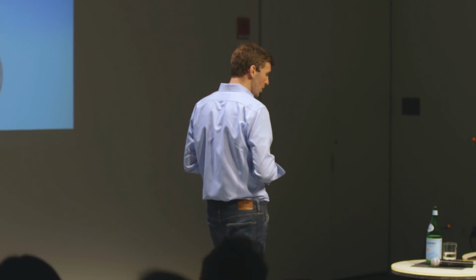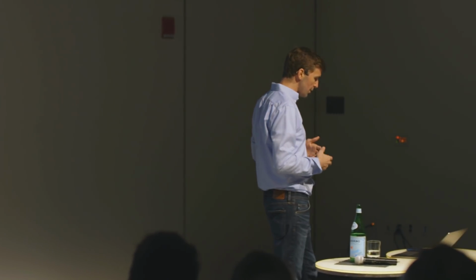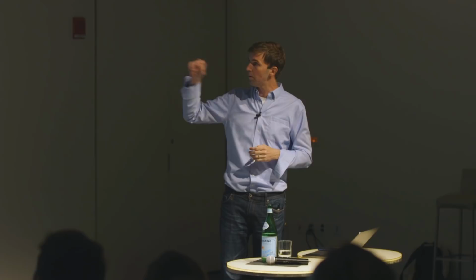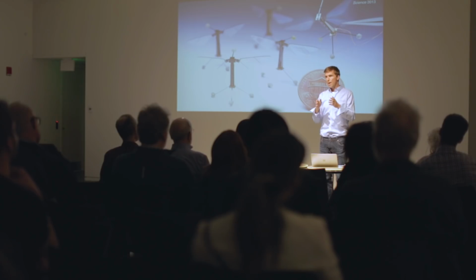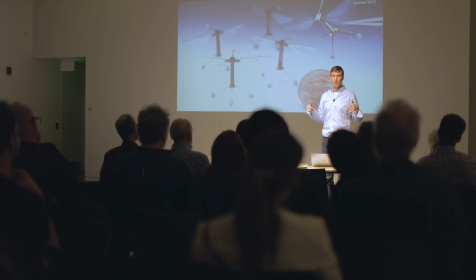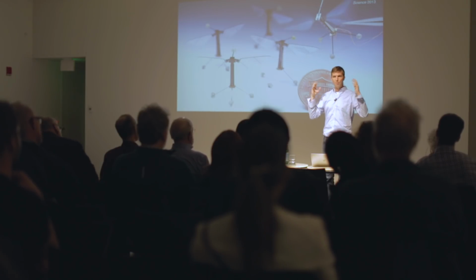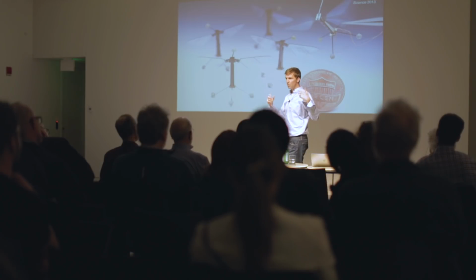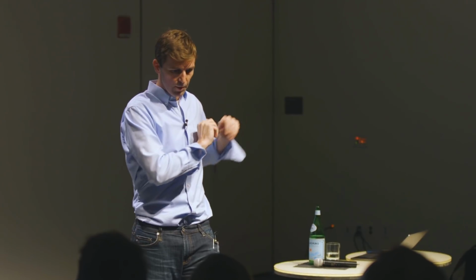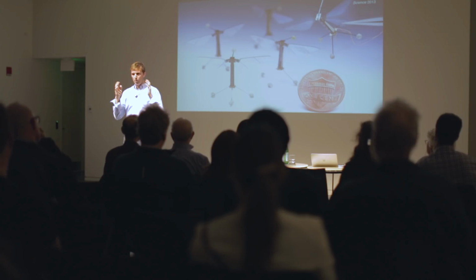So then the question of design. How do we actually think about designing these systems? This is a very simple device. The way that it works is I cut the robot down the middle, and I have an actuator on either side, and that actuator is basically just a little artificial muscle that's doing this. That very small motion is then mapped through a flexure-based transmission mechanism. It's just a gearbox without the gears, because those wouldn't work, and I'd be happy to tell you that offline. And then that little motion gets amplified into this large flapping motion.